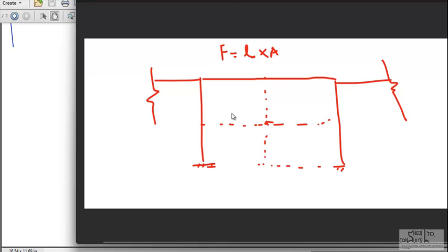Then for flexible structures, you have to calculate the external and internal wind pressure coefficients as well, and then you get the corresponding windage zones. You have zones A, B, C, D, E, and so on, defined by the code. But I want to specifically explain how the exposure coefficient is evaluated.